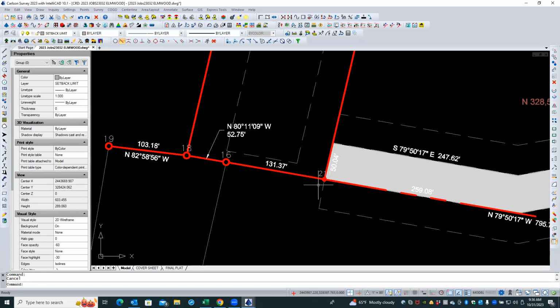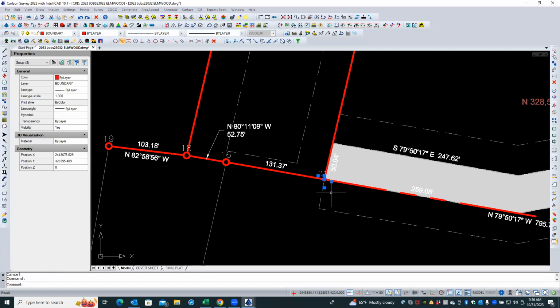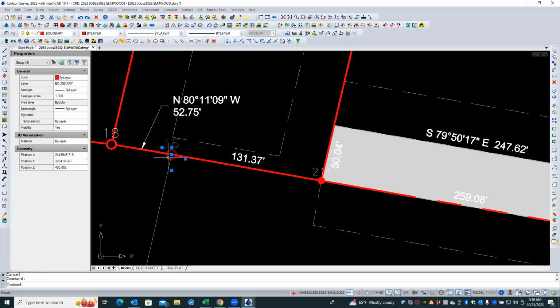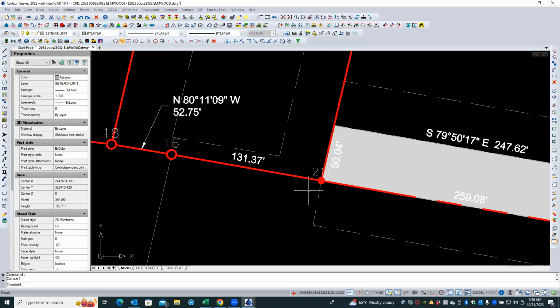Just in terms of CAD work, I could select that particular block and change its scale. Here it's at 0.08 because it is annotative, so that one's actually correct. But this one is probably not annotative. See, it's not annotative and its scale is 8. And I can't change it to be annotative because it's not the same block definition.